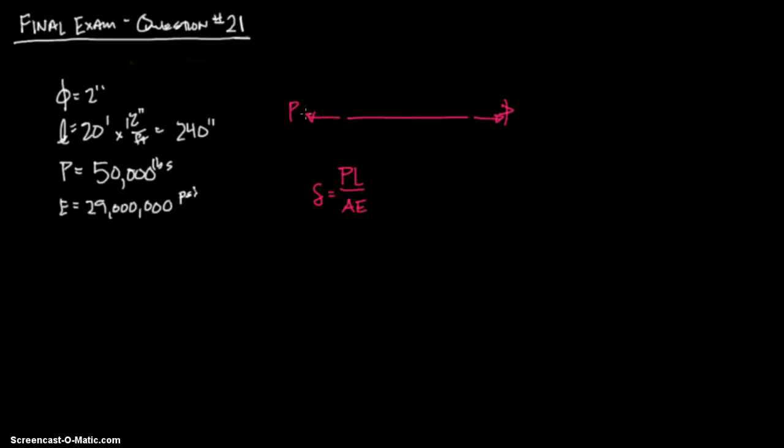This P is your P load, is your tensile load or compression load, I guess. L is your length, your original length. A is your area of your beam or bar or whatever you got. Then E, as we said, is 29 million. And that's kind of your stiffness of your beam. How easily would it stress? It's E equals stress over strain. It's Young's modulus. Alright.